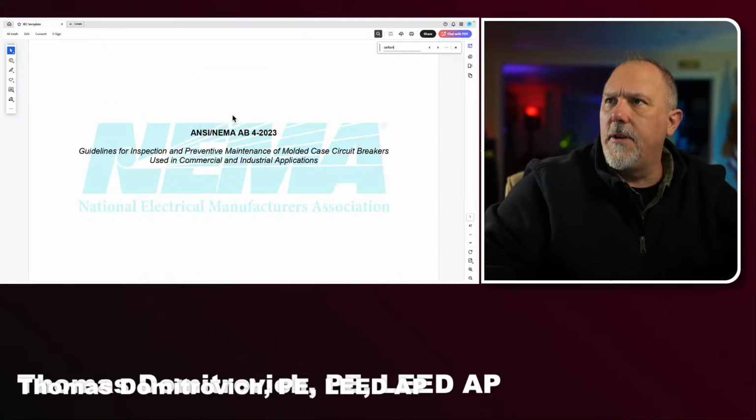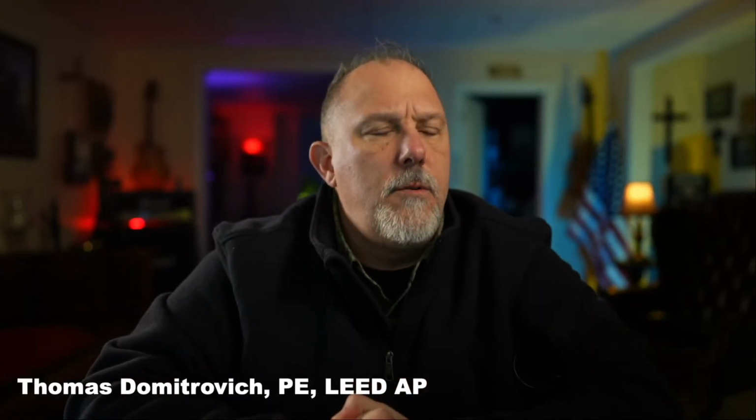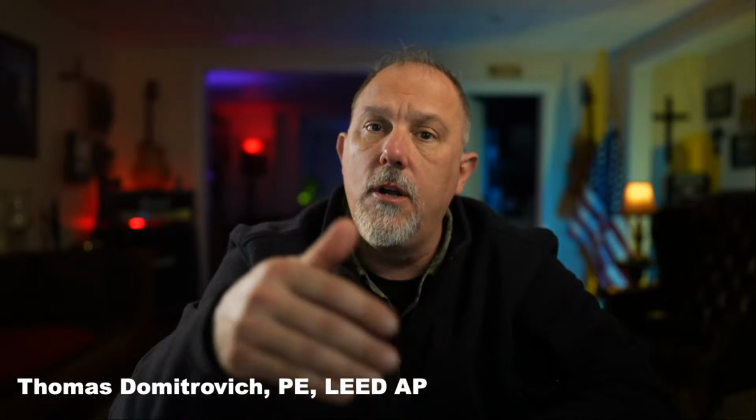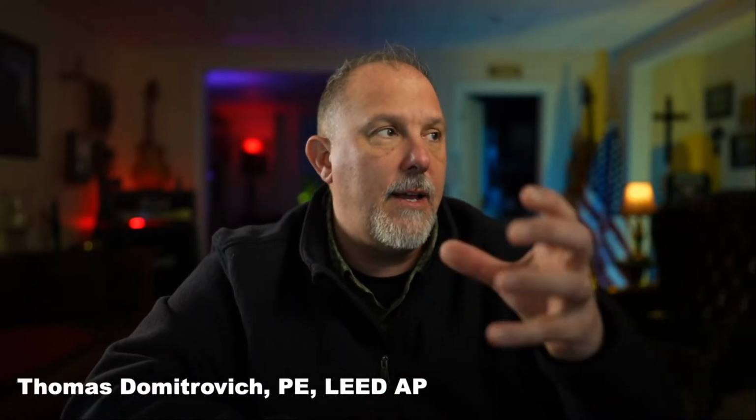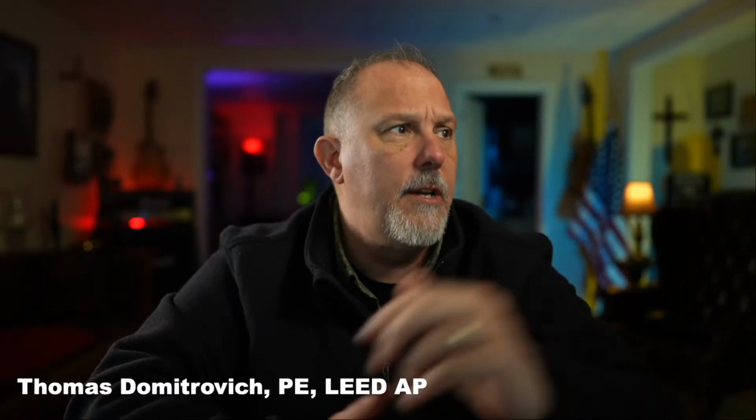There's no carbon in there. So if you read down through this document, I'm trying to make this shorter because I've got a couple minutes. What I would suggest is that you take that circuit breaker, because it was a short circuit, it's a fault, it's not an overload, so you're not sure what currents that circuit breaker interrupted. You've already said that you've looked at it at the vent ports, and there's soot or carbon dust.